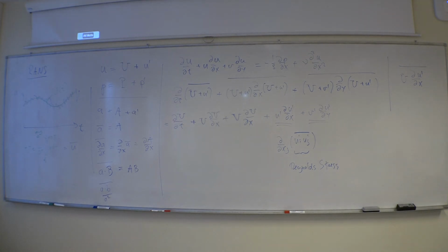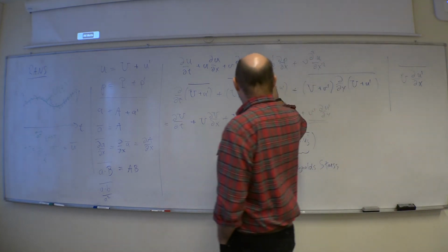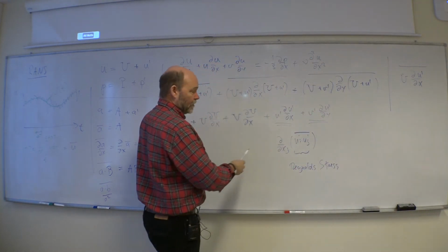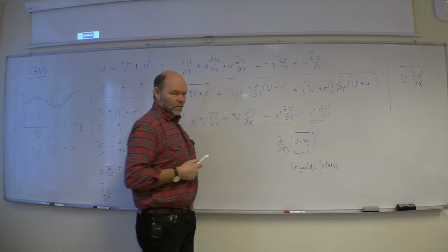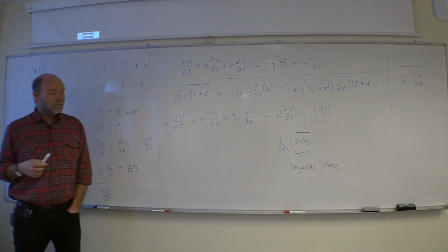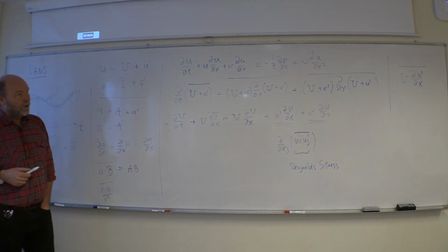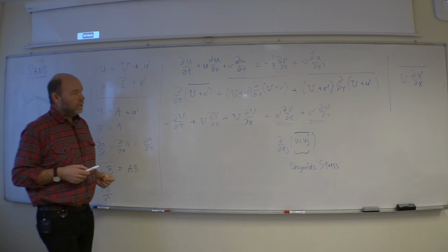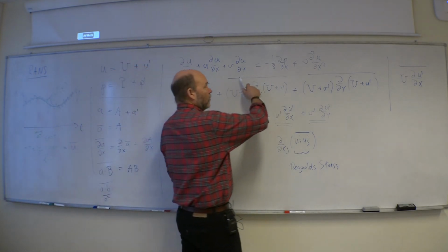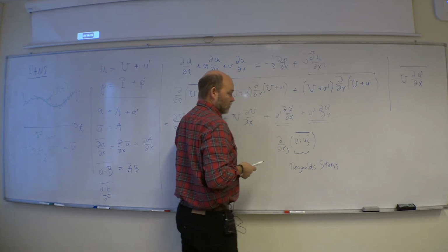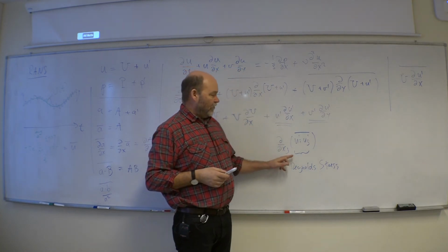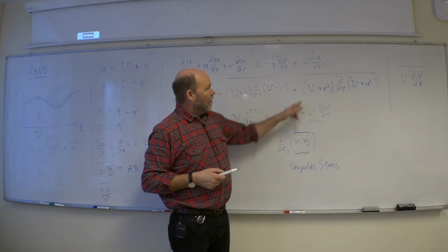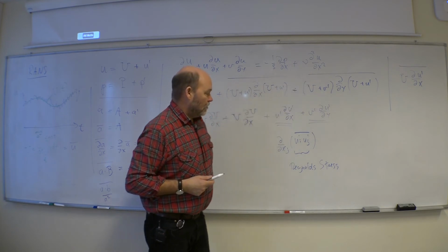And then we throw them on the other side of the equation sign in the Navier-Stokes. So they are actually accelerations due to turbulent motion. That's where they are born. But we will throw them on the other side and join them with the viscous stresses inside this term.